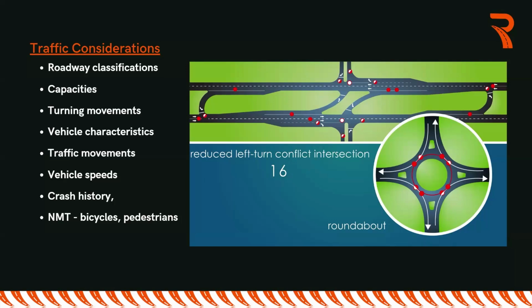And the design speed, the junction design speed, is the principal design parameter upon which the geometric layout and the capacity of a junction is based. What this means, for example, if you see the intersection at the top, which is basically more of displaced left turn lanes, it means that vehicles can move at considerably higher speed compared to roundabouts. So when it comes to a roundabout, you are expecting a very low speed. The whole idea of designing roundabouts is you want to reduce the speed of the vehicles so that they can move through the concentric movement at slow speeds.